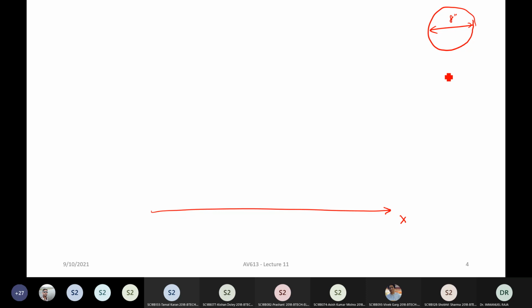Now, what happens is when it goes through different processes, like diffusion, polishing, and heating, in some of these processes there can exist certain gradients along the x-axis, or a gradient along the y-axis. In fact, it can be along any axis, which can be decomposed into a gradient along the x or y axis of the silicon.